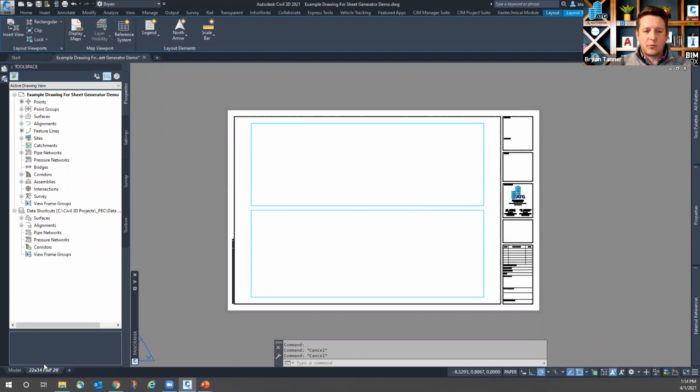So oftentimes, if we work sometimes in an ANSI D and architectural D, or maybe even architectural E drawing, we would have to have 3 different layouts, one for each sheet size. In addition to that, we would need to have layouts representing each of the scales that we typically work in.